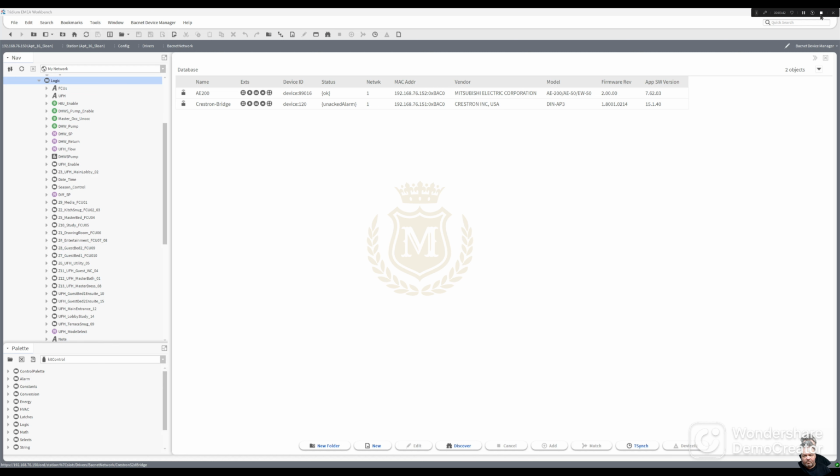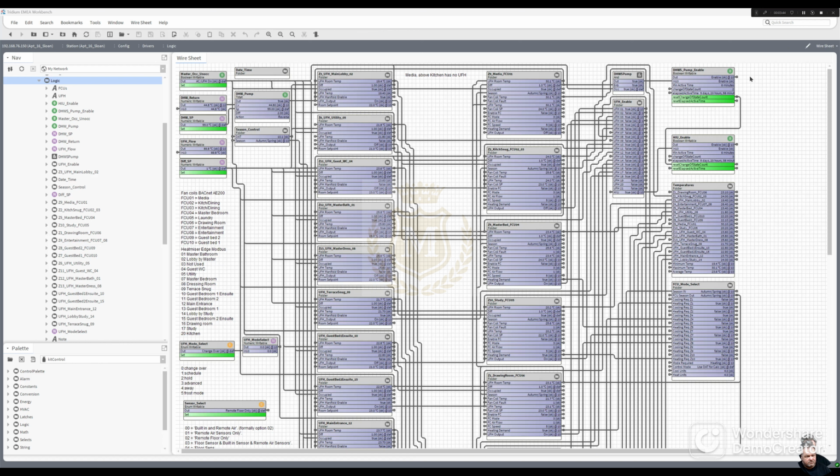I think I'll just pause you. So there's the logic. I've got different folders for the different rooms. So that's my underfloor system. That's my Fanco systems, which has got underfloor built in there. And I'm just doing some calculation of the temperatures, minimum, maximum, and average. Selecting what mode. So we're working in outside air temperature, and we could work in demand.